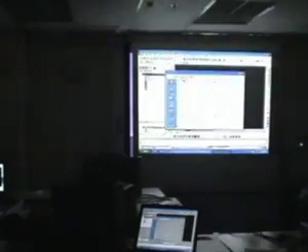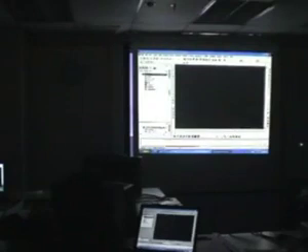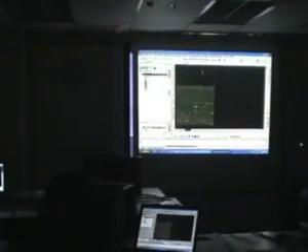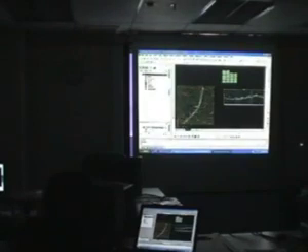Instead of starting from scratch, I'll open up a drawing which I already have, just to show you the major difference. The bit about converting 2D to 3D can also be done in Civil 3D using the same methods, because Civil 3D actually comes together with Map. You can see the workspace at the bottom here. You can use that to convert 2D to 3D as per the Land Desktop method I showed you just now.